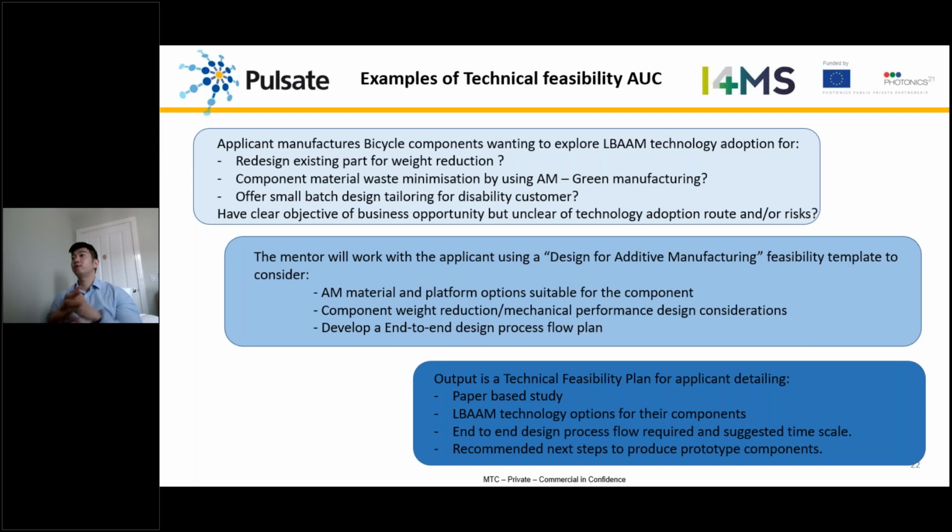And also, how do you design a component like this to enable it to be built with a laser-based AM machine, because that is very different from your existing, let's say, CNC CAD design methodology. The mentors will also be able to help you develop an end-to-end design process flow. Because additive manufacturing is not just building, there are a lot of different things associated with the pre-process and post-process.